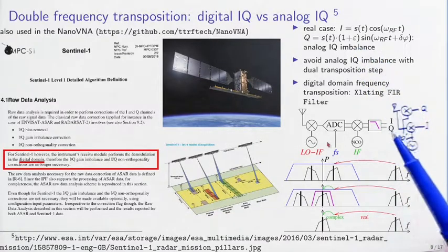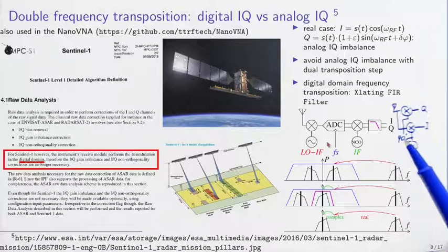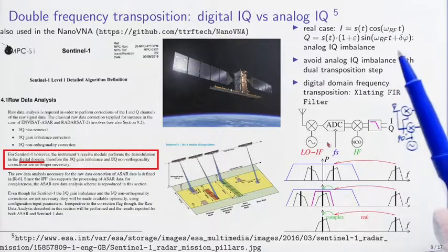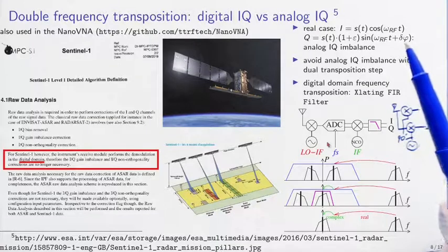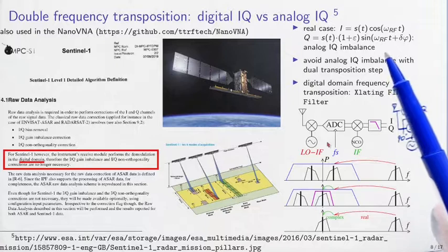And furthermore, it is extremely difficult to keep this 90-degree phase shift on a broadband. If you imagine that you would create this 90 degrees by using a length of coaxial cable, that would work only at a single frequency, and typical IQ receivers will require that the local oscillator is at twice the frequency so that they can run 2 copies of a clock shifted by 90 degrees following the division of a frequency by a factor of 2. So this means that the I and Q components might exhibit a slight phase shift delta phi here, which are both called IQ imbalance.